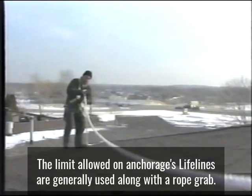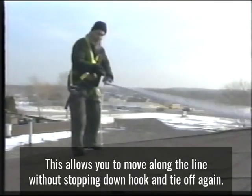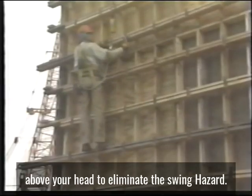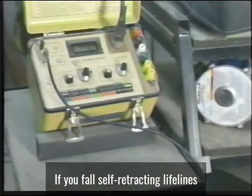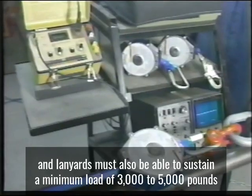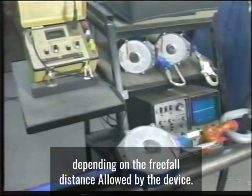Lifelines are generally used along with a rope grab. This allows you to move along the line without stopping to unhook and tie off again. If a self-retracting lifeline is used, keep it directly above your head to eliminate the swing hazard if you fall. Self-retracting lifelines and lanyards must also be able to sustain a minimum load of 3,000 to 5,000 pounds, depending on the free fall distance allowed by the device.